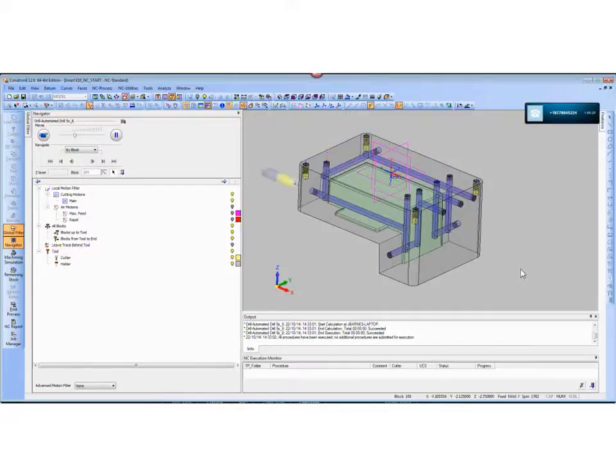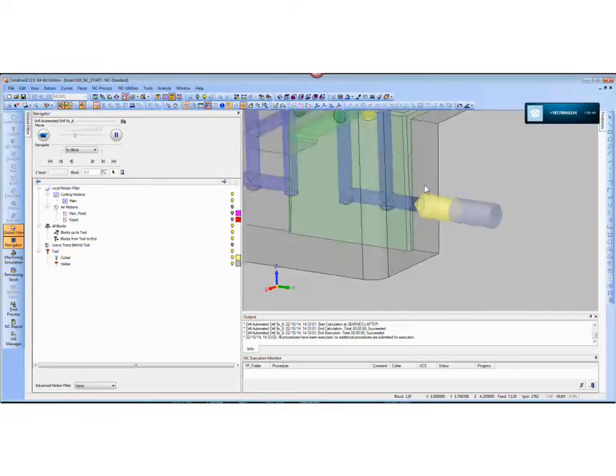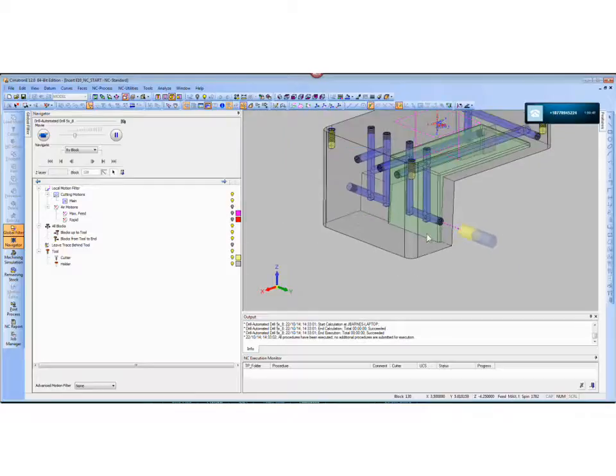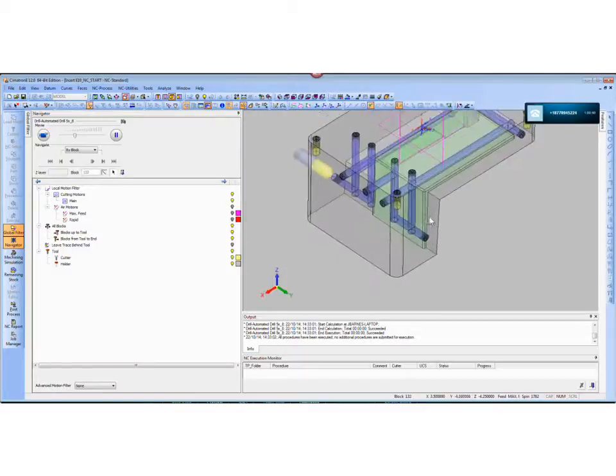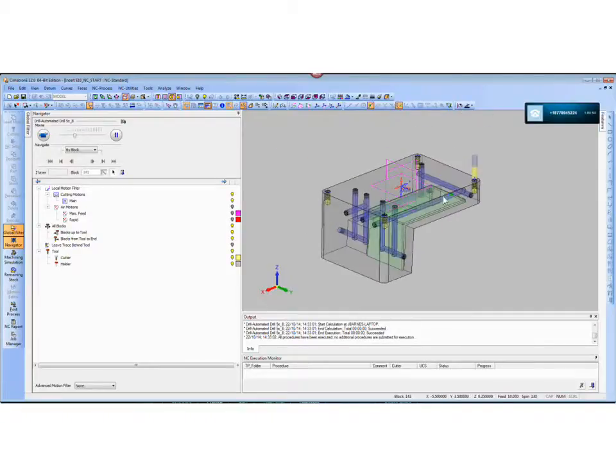Now these water lines I am processing with a starter drill, but it's really for 2 reasons. Number one, I want to have a big chamfer lead in on these holes. I think that's an advantage. And secondly, you're going to see some logic being used here in a minute. This is the tap drill coming in and tapping these holes. But in a second, you're going to see that not all these holes are drilled in the same way. Even though I use the same sequence, the sequence can have logic built into it, and I'll explain that in just a second.